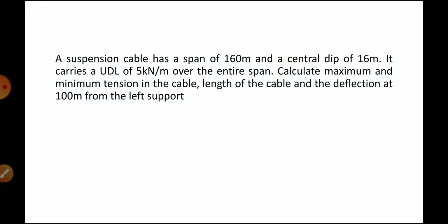A suspension cable has a span of 160 meter and a central dip of 16 meter. It carries a UDL of 5 kN per meter over the entire span. Calculate the maximum and minimum tension in the cable, length of the cable, and the deflection at 100 meter from the left support. Okay, so in university question paper, often only the statement will be given,